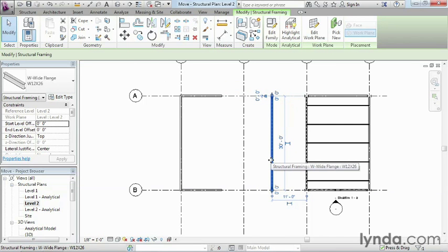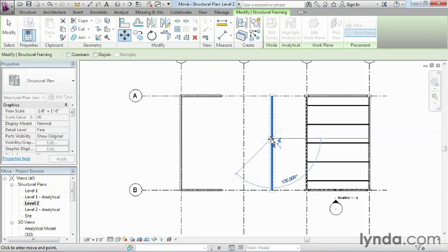The only reason why I tend to not use that form of the move command as opposed to just a normal move command is usually if I've drawn something in, I usually know roughly where it's supposed to be at. And as a result of that, I know if I want to use move, I probably know this should be moved over 1 foot, 2 foot, 3 foot. And you can only do that using the normal move command as opposed to just holding down on the object and dragging it to wherever it is that you feel like dragging it to.